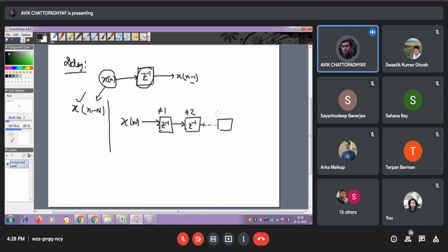In this way, you require n number of delay elements, where every delay element in its turn gives you one sample delay. As a result of this cascading or series connection, the output is obtained after passing the signal through these n delay elements. Individually they are the unit delay elements.